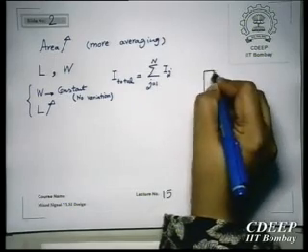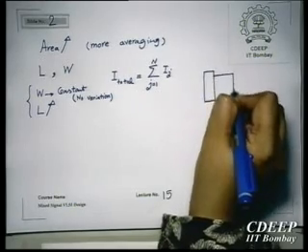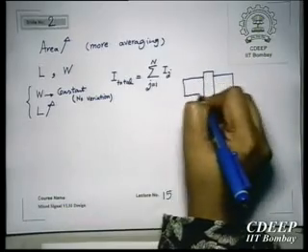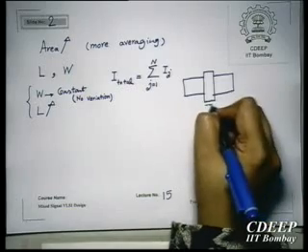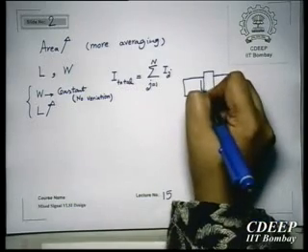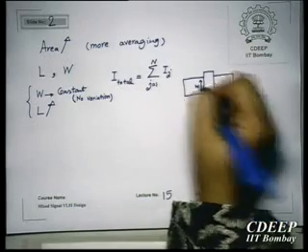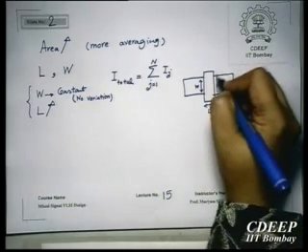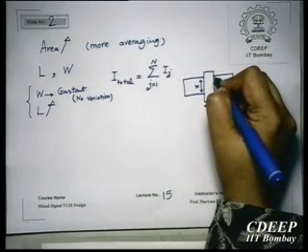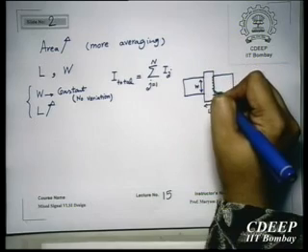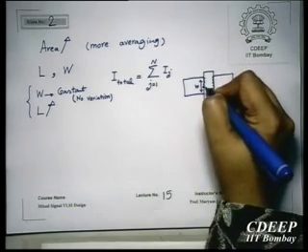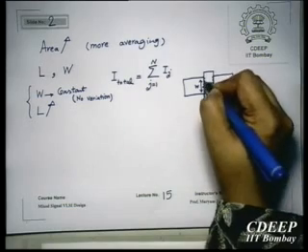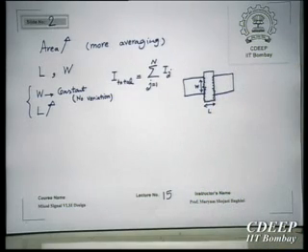It means if you look at the layout of the transistor, this is L, this is W, right? So I have change in L. What does it mean? For example, the first thing will be poly roughness, right? Because of this roughness, I don't get exact L everywhere.